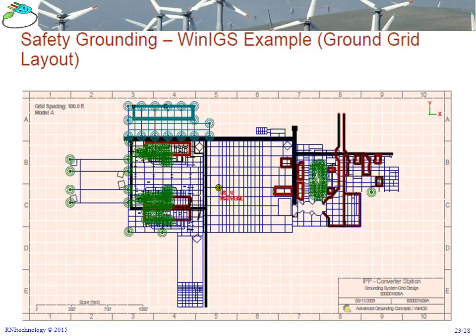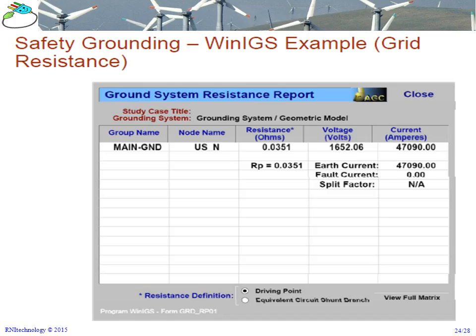And that would be the grounding layout in your system. Like you have a substation, you add different ground rods, which you will see here in green, whereas you have different bare conductors which you see in blue. Then you perform your analysis. Your analysis should cover the main safety items, which are ground potential rise, step and touch voltages, and you will see that with the calculations in the next slides.